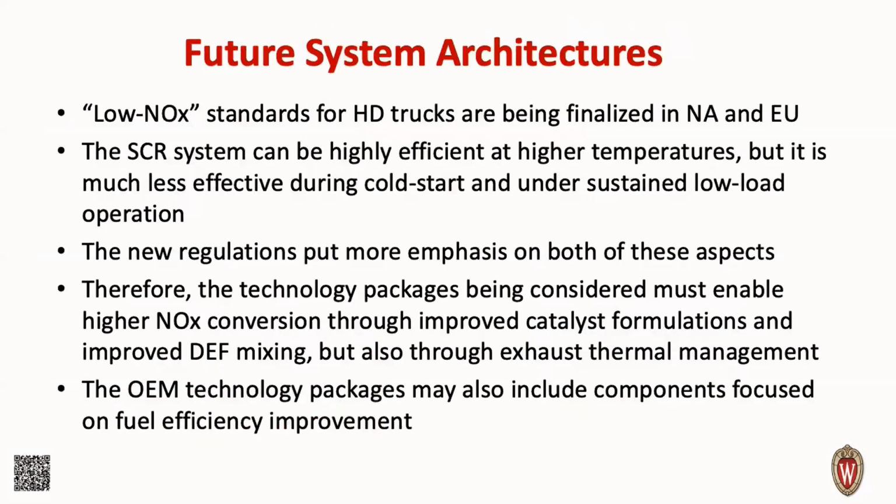So looking at future system architectures, the low NOx standard for heavy-duty trucks is finalized now in North America and Europe. The SCR system is highly efficient at higher temperatures, but it's a little more challenging during cold start and under sustained low load operations. So trucks driving at low speeds, maybe through town delivering vehicles. The new regulations put a lot more emphasis on both of these aspects, because these are times when a lot of emissions are coming through.